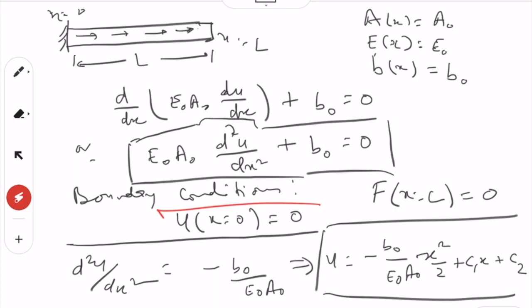In any case, we need two boundary conditions to solve a differential equation of order 2, right. We have to apply them here because we are solving the differential equation, like we are integrating, hence we will need it. However, when we have the matrix form, when we apply finite element analysis, we do not have to apply it; automatically it is assumed equal to 0. If there is a force applied, then you have to enter that force. You also did this when solving the truss: wherever the force is, you put the force, otherwise there is no force, then you put 0, right.